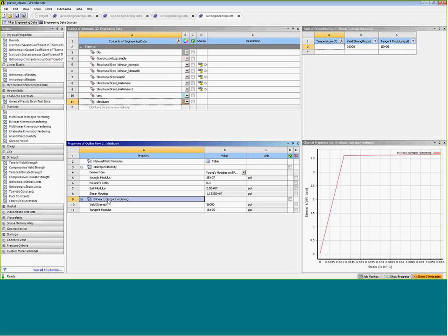You do not want to put a 0 slope in, because a 0 slope will give you computational convergence issues. So you notice I put in a value, in this case of 1e5, which is a fairly large number, but relative to 30e6, it's a fairly small number. So this gives me, in a sense, the effect of very little hardening. So it's essentially an example of an elastic, perfectly plastic response.